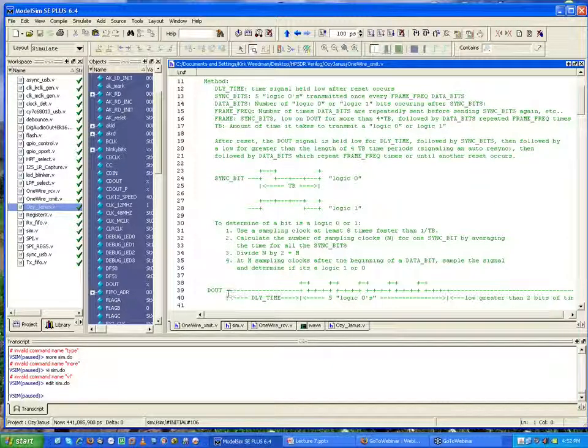So my format is going to be, well, initially when you turn the boards on, they may need to do some stuff to get themselves initialized and ready. So before I transmit anything from Aussie to the other boards, I'm going to wait some delay time. It's just a single wire, and Aussie's the one transmitting the data out. It's called D out.